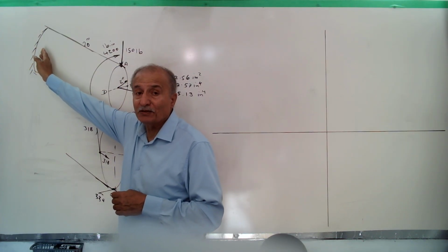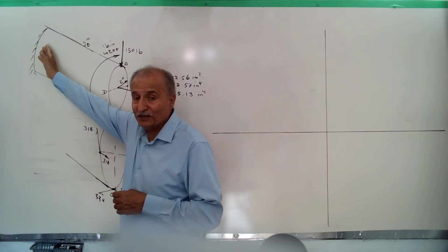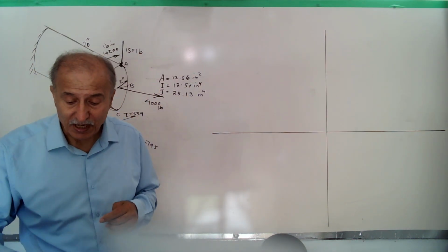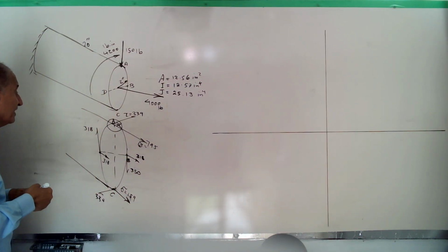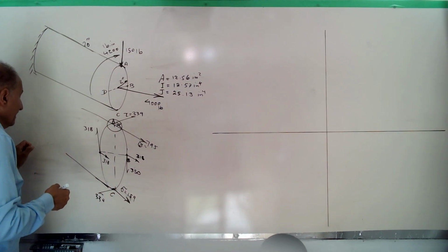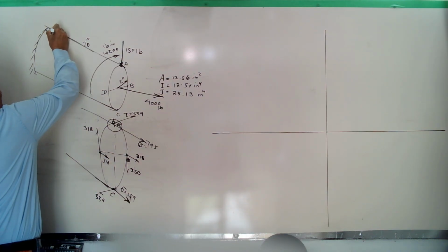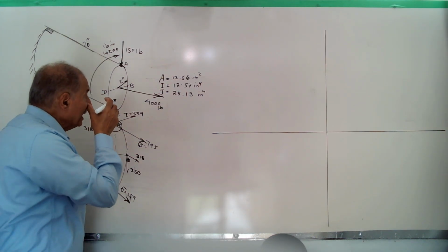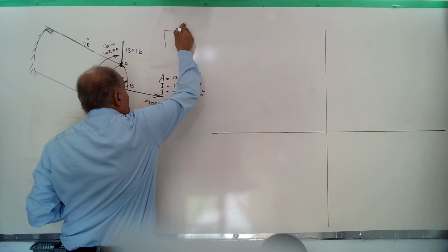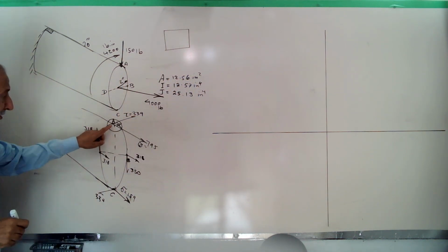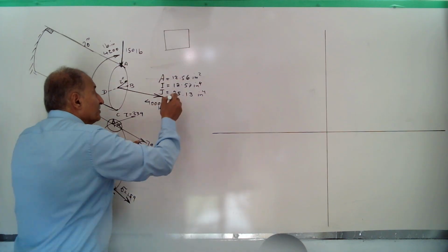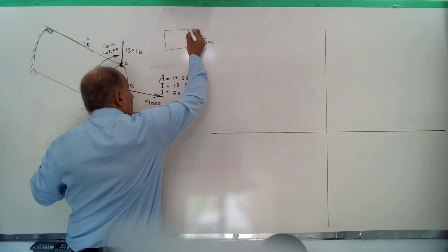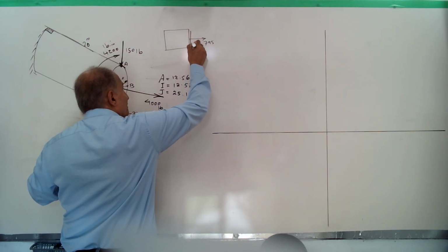And because bending is maximum at the base, the fixed end of the shaft, we consider elements at points A and B and C, D over there. For an element at A here, the state of stress for this element is what I show here: normal stress 795 and shear stress clockwise 334.